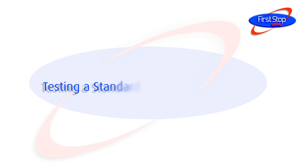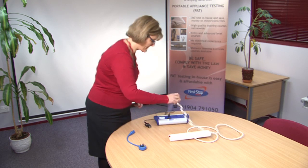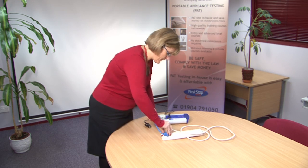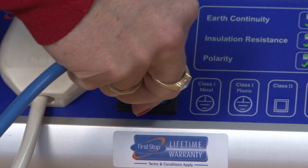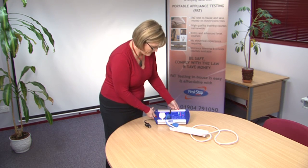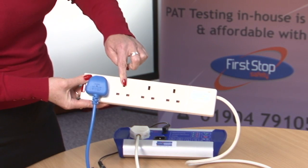Testing a standard mains extension lead. If a PAT tester has an IEC test facility, then this can be easily adapted to carry out a mains extension lead test as well. All you need to do is connect the short IEC lead to the socket of the mains extension back into the PAT tester as shown. It's important to test all the sockets on a multi-way extension lead in case one of them has a poor earth connection.